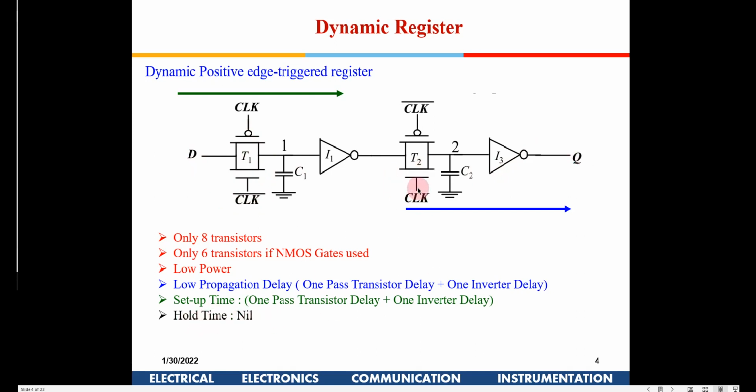When the clock edge is going high, you are permitted to change D, and nothing would happen here, because my purpose is to sample data which is previous to that, and I do that by disabling this particular transmission gate. The moment the clock goes high, I disable the transmission gate, so even if D changes, that doesn't get reflected here. The previous data, whatever was sampled here, only that will be available here. That is how the hold time is nil.